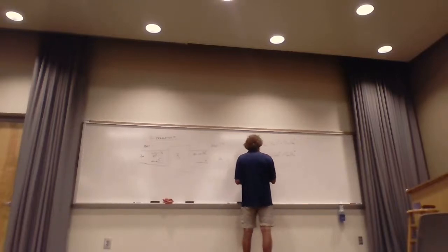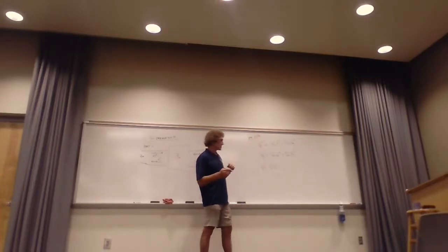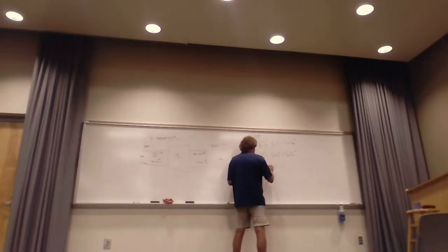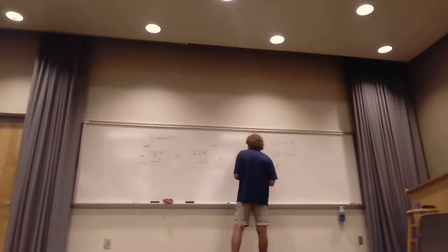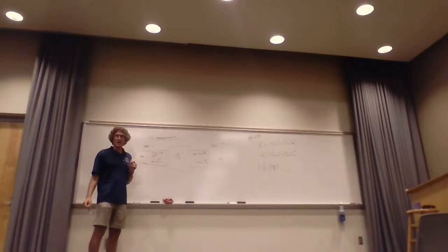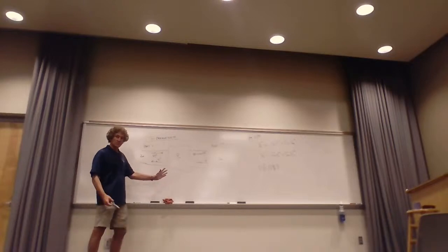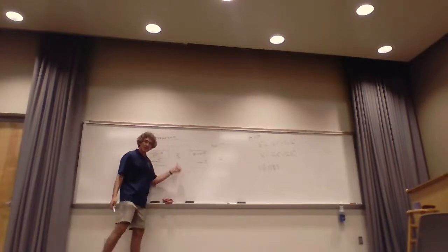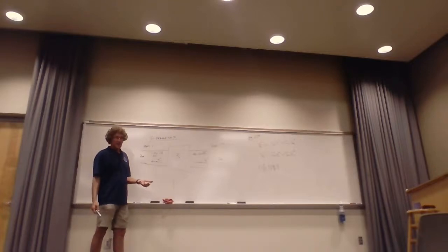All right, a lot of times they'll do it like this. They'll put blocks or they'll put brackets, something like this. And the reason is this is a 2-port. There's only 2 ports. There's 2 ways for information to get in and out of this S block. Now, the truth is this, you could have N ports. You could have 3 ports. You could have another port here. Things coming in and coming out. Follow me? You can have as many ports as you want, but you always start with 2 ports. And a 2-port device is very common.